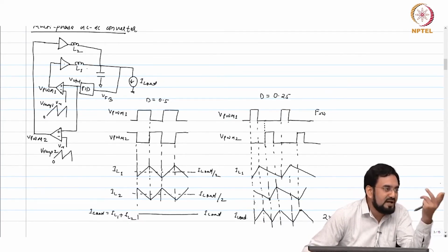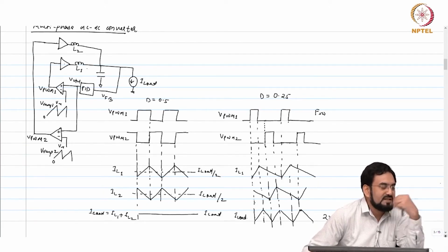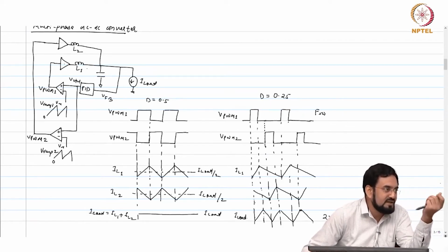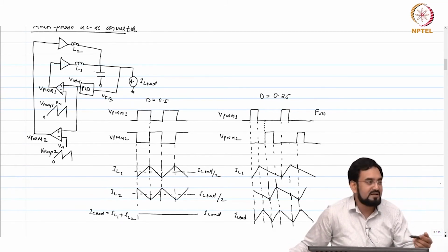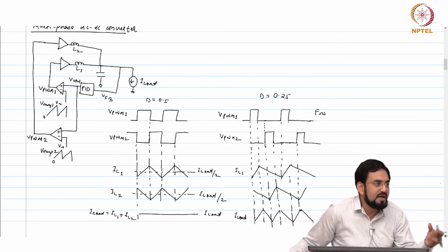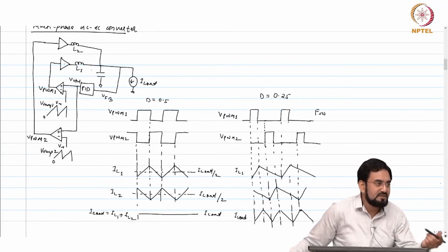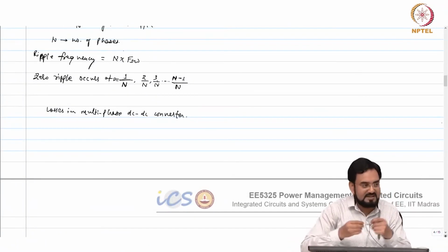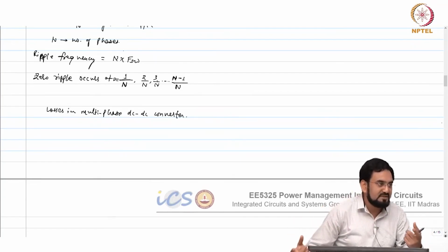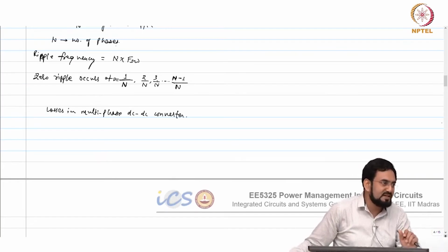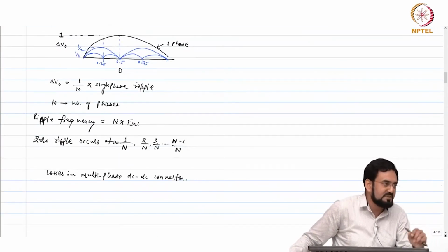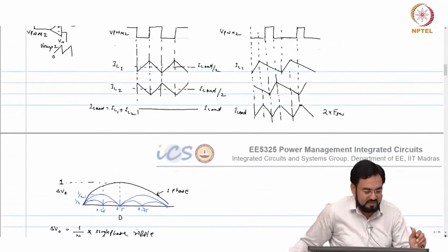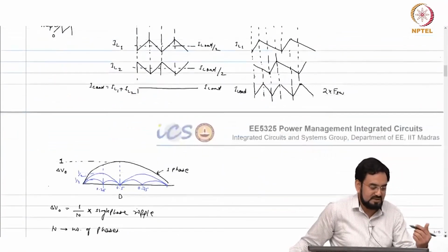So, what we can do, we can use a higher DCR inductor that will have a smaller size. Lesser the DCR, bigger the inductor is, because it requires thicker coil. So, low power inductors will be smaller in size compared to high power inductors. So still you can reduce the size of the inductor. Maybe after packaging it may not scale by 2x, but still maybe 20-30% reduction you can still see by using lower power inductors here.